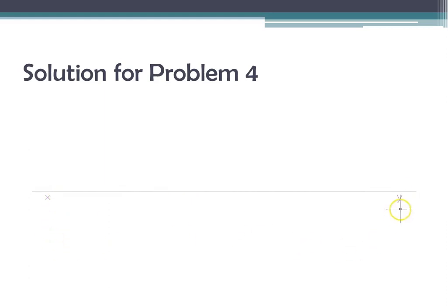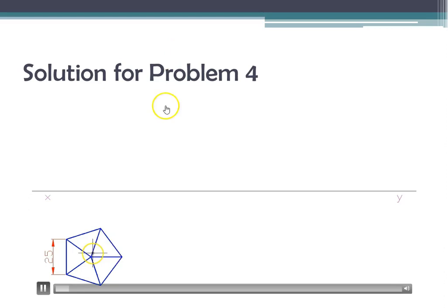So we'll draw the hexagonal pyramid in simple position first. So please note that we have drawn the pyramid in such a way that its corner is on the right hand side, because the question says that it is supposed to lie down as if it is lying on the slant edge.